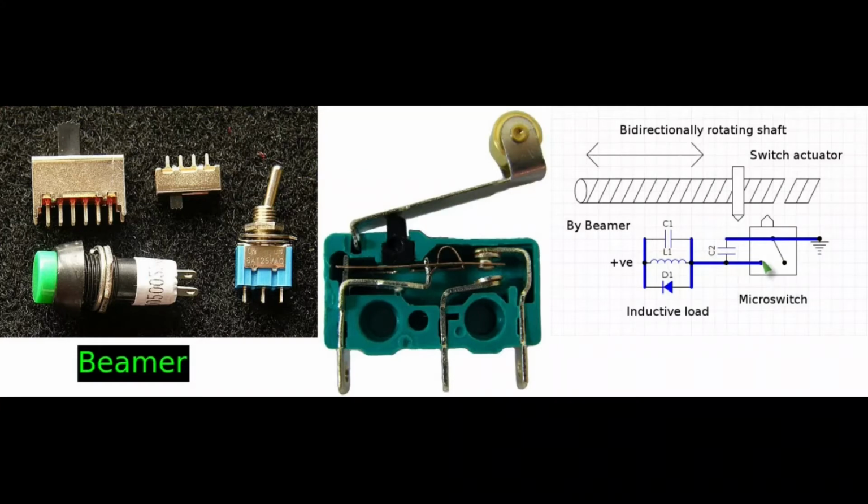So the manufacturer of the micro switch recommended an anti-arcing capacitor here, which is C2, and the motor manufacturer recommended a specific diode for the back EMF, and also C1, a capacitor across their solenoid stroke motor.